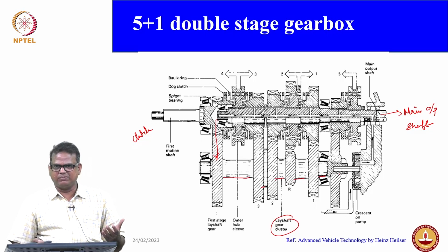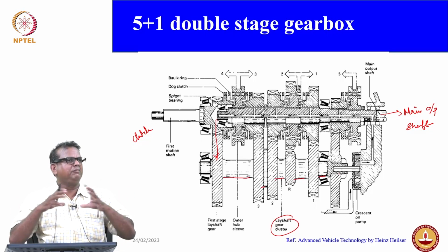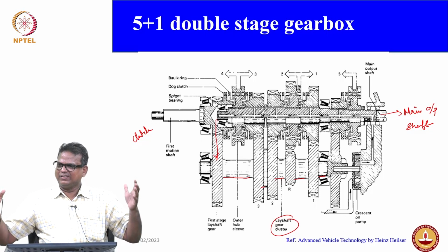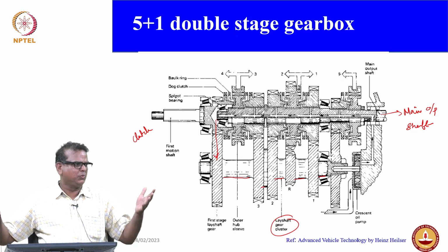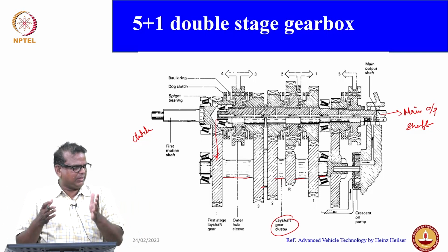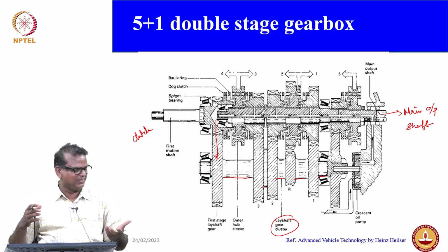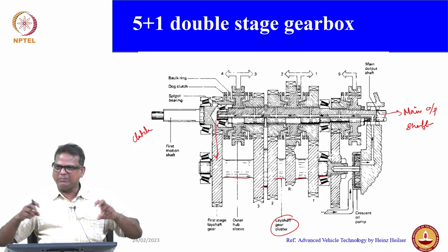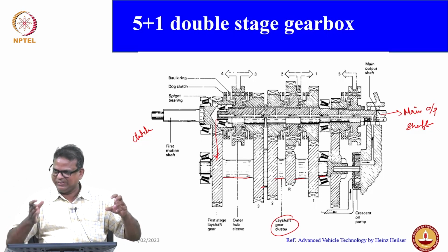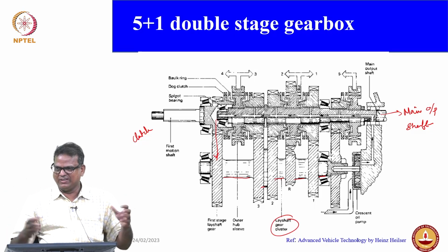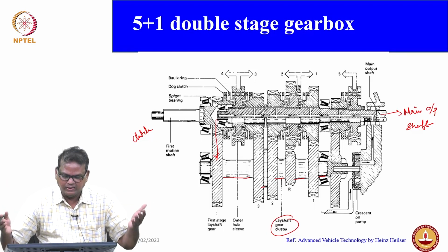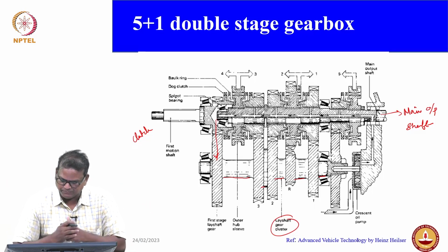No, right? It is a variable, right? If you have a uniform shaft, what happens? With a uniform diameter, the shaft is very heavy and mass is also going to be added, which you do not want. So, wherever the load acts, that portion alone you can maintain the diameter, and the remaining portion you can minimize. By doing that, you are optimizing the shaft diameter at the load acting positions in such a way that the volume and weight will be reduced.